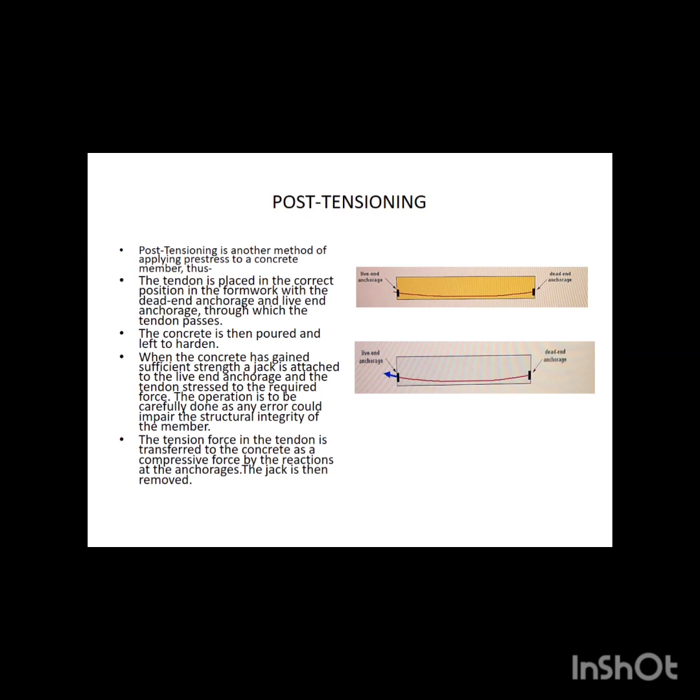Post-tensioning. Post-tensioning is another method of applying stress to the concrete member. The tendon is placed in the correct position in the formwork with a dead end anchorage and a live end anchorage through which the tendon passes. The concrete is then poured and left to harden.